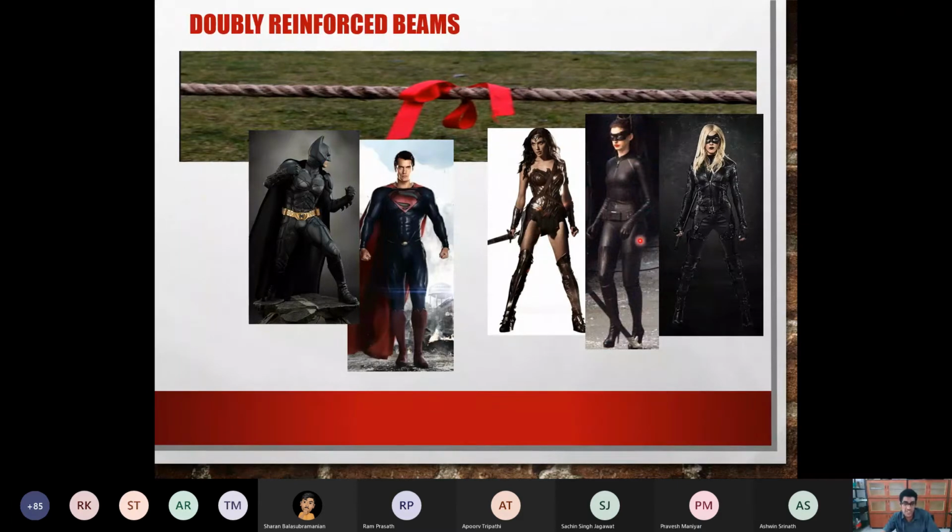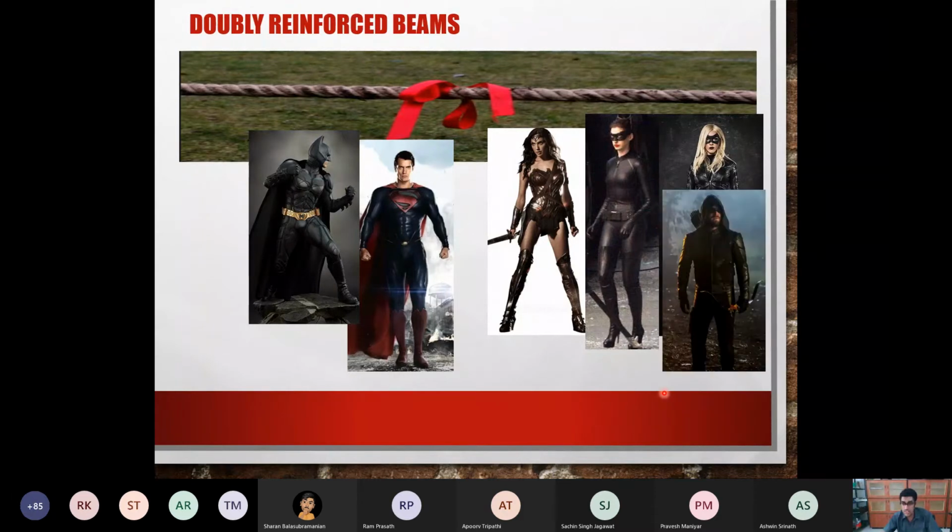Right. So you need additional help at the right to restore equilibrium, to keep it balanced. In concrete terminology, to keep it balanced, you need additional reinforcement on the side. If you give additional reinforcement, then it is going to get balanced and this side will not be crushed.